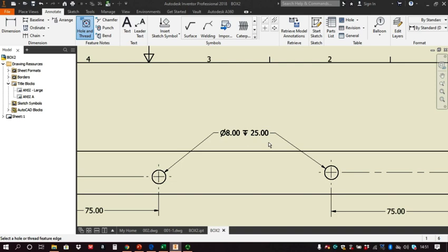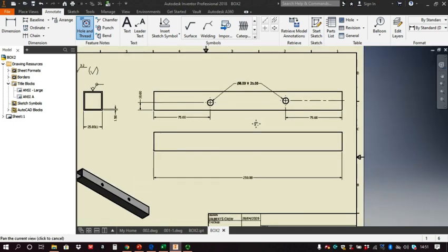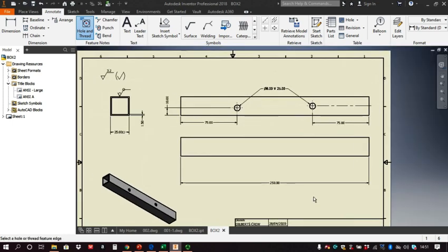Okay. If I'd have left it at 350 mil, this would say 350 mil here, and you'd have somebody going out trying to find a 350 mil drill bit so that they could actually drill 325 millimeters of air. So absolutely pointless. Yeah. So we try and get our depths right. Now, is there anything missing from the dimensions on there? And I'll just give it a quick look over, and I think we're pretty much there.